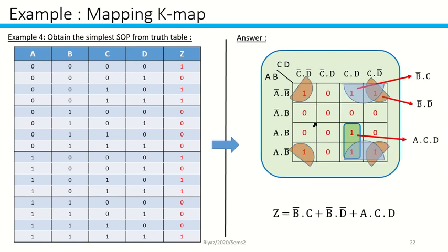And then later on group it. So you have formed the orange connection grouping of 1s. You have one group, the second group will be the blue color, and you also have the green color. So you have three possible groups, and when you have these particular groups, you can add them up to form the SOP of this particular K-map.